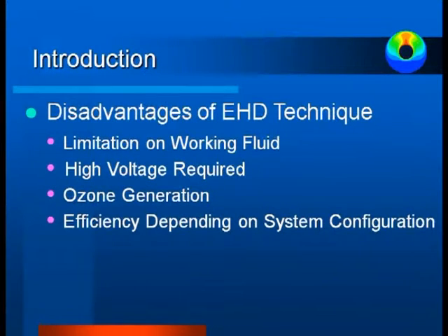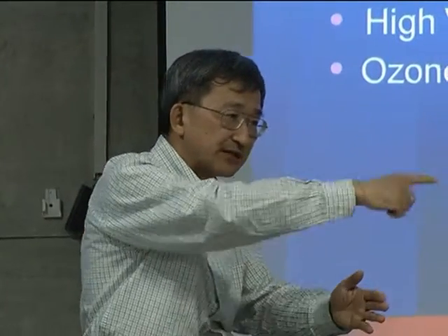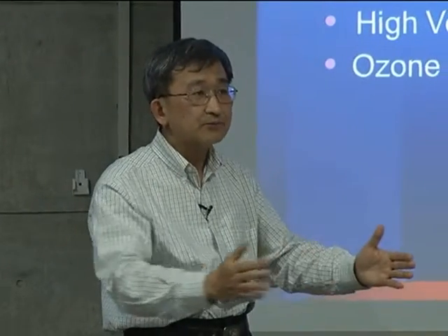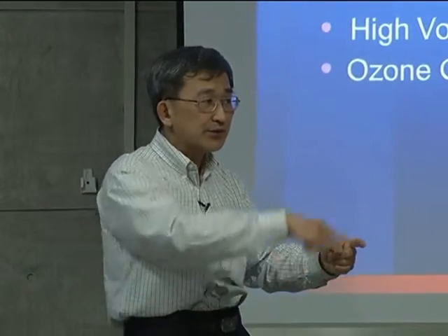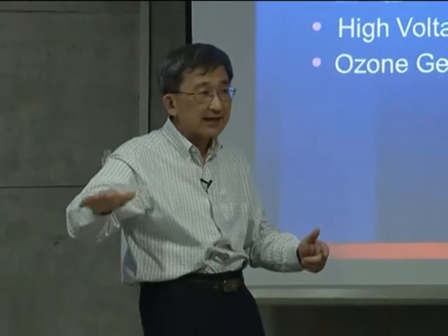Unfortunately, when we apply high voltage, it usually will create ozone. Ozone will be generated in this high voltage application, and ozone is not good for human health. But we studied this and found that ozone is a very active agent, so as long as you're not too close. In our lab, we do ozone concentration measurements. If you are away from the source, 1 meter or 2 meters away, the ozone concentration will decay to ambient level.